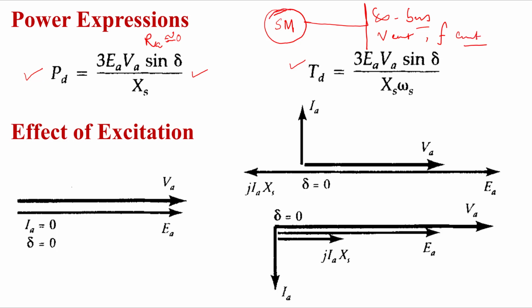So when it is connected, the terminal voltage of the synchronous motor will be constant as it is connected to the infinite bus, right? Now, what will happen if we change the excitation of the motor? Let us say it is operating at unity power factor. Okay, first the normal condition, where you can say normal excitation.